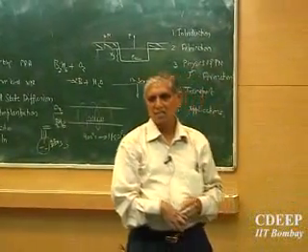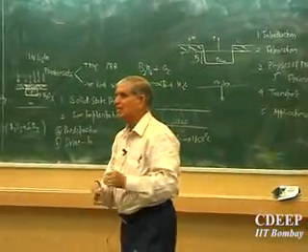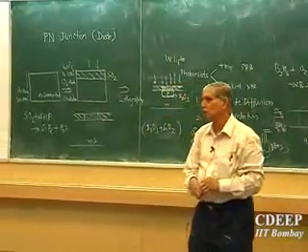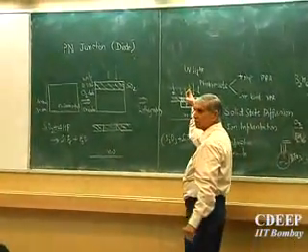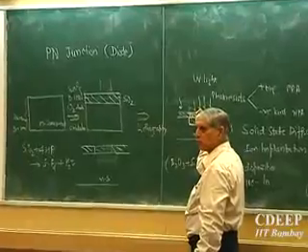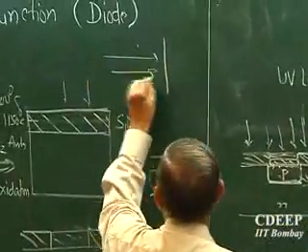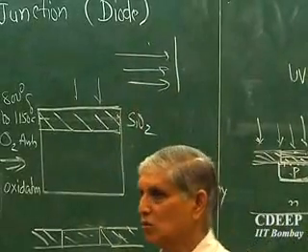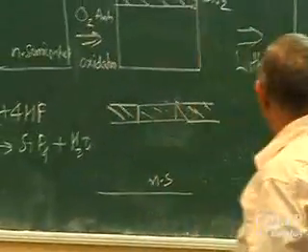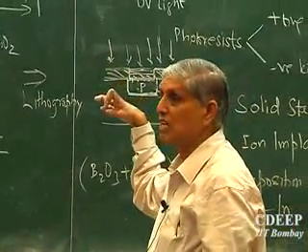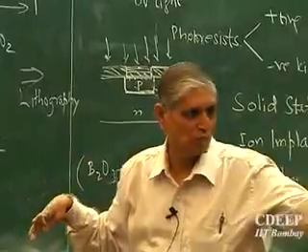get energized. Then using a magnet, using Lorentz force, I can decide at which angle the beam should come for the ion, and it should strike vertically, orthogonal to the wafer. That means if this is your wafer, ions must strike orthogonally. Once they strike, they have energy of 300 keV, very large energy.